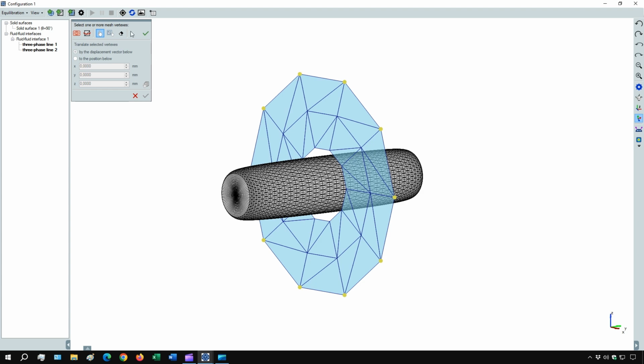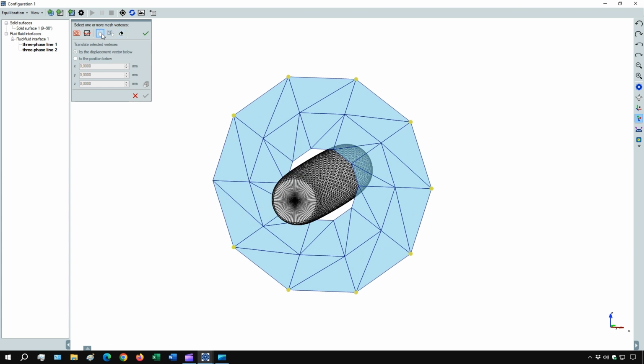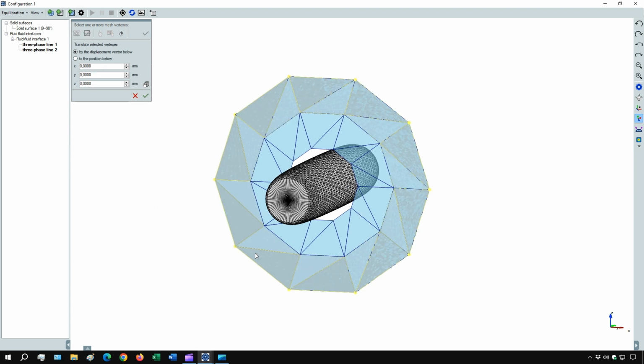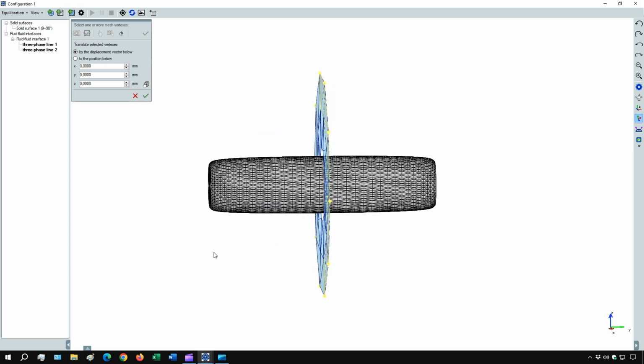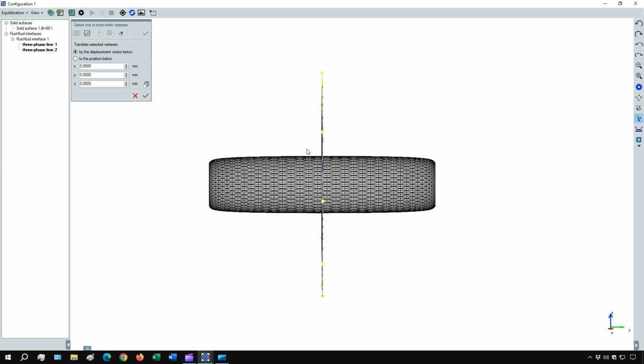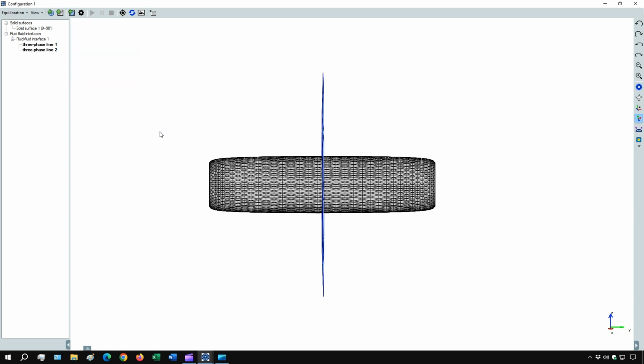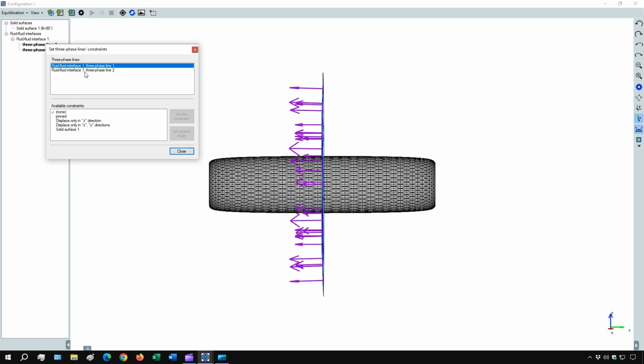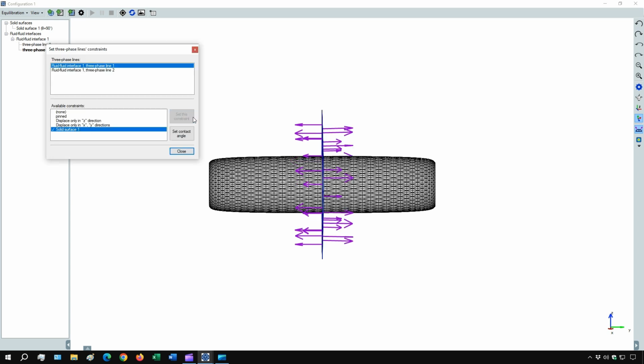I do this so that, when we select the cylinder as constraint for the two boundaries of this fluid interface mesh, the obtained toroidal droplet will not have an exactly zero volume, but slightly larger than zero, so that we can easily discern which is the fluid below the fluid interface. As indicated by the mesh's normal arrows, the fluid below the fluid interface is that to the right. So, when selecting the cylinder as constraint for the mesh's two boundaries, the fluid below the interface will be the fluid inside the toroidal droplet.